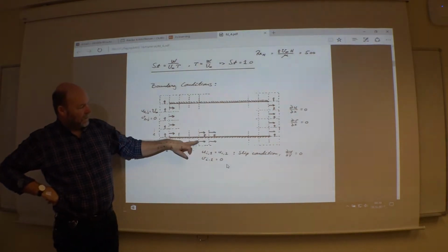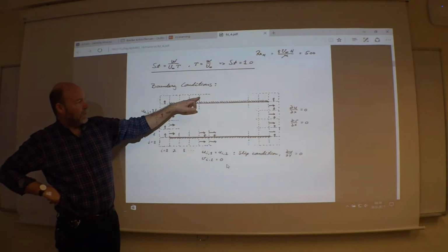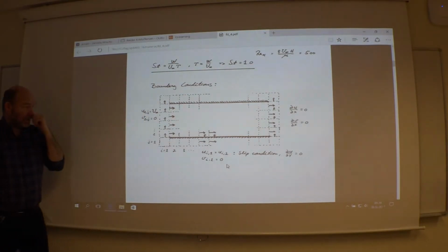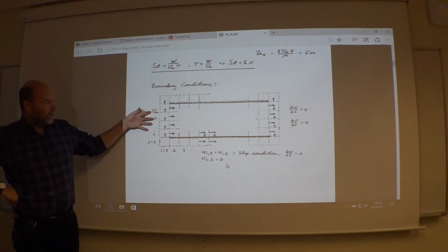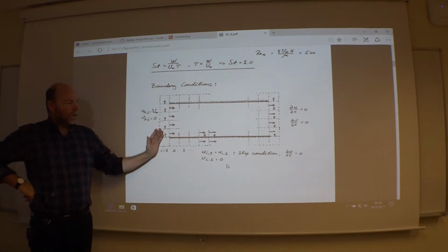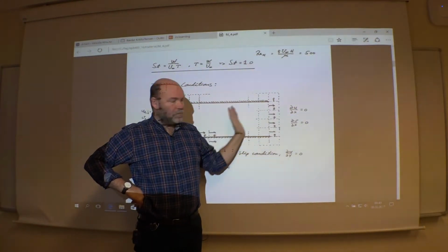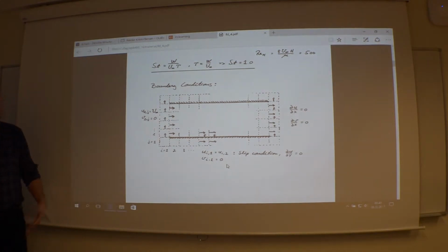So I just set the velocity, the ghost cell down here, equal to the one inside, and same above here. Inlet, that's easy. You just say x velocity is 1, y velocity, you set him to be 0. And the outlet, both Neumann conditions, derivative equal to 0. So that is the state.